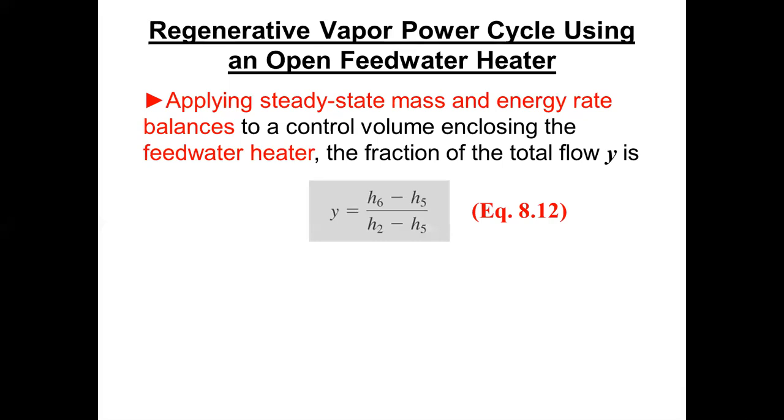And so that's that. When we work these problems, and if you're not given these extraction amounts, then you have to go back, and you always go to the high pressure heater first. That will be the easiest one, and then you work your way down in pressure, because some of the lower pressure heaters may have some of the other extractions involved. The high pressure heater will only have one extraction involved, and you've got all of the mass going in the feed water put back together. So that's the rule of thumb.